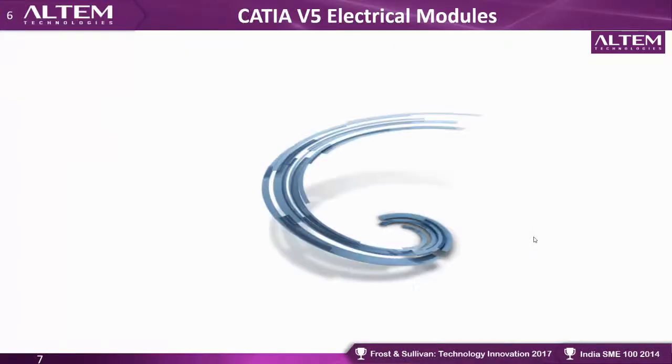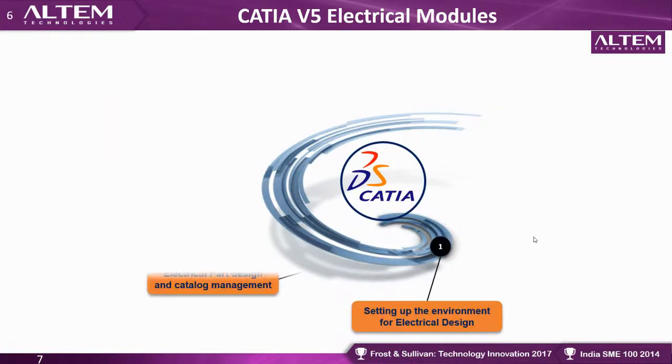So these are all the basic settings which are done one time. So now we are good to go for our part design and harness creation. So next module in CATIA V5 in electrical design is electrical part design and catalog management.